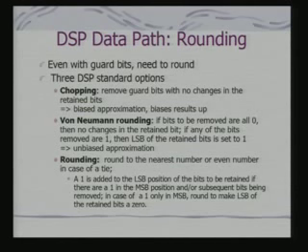So, if the LSB of the retained bits is already 0, by 1 we are moving toward positive. If it is already 1, we are not moving towards positive. So, there would be a negative error. So, it is a kind of an unbiased approximation. But obviously, the approximation error would be pretty high, because I am changing just the last bit, that LSB, depending on the bits which are getting truncated.